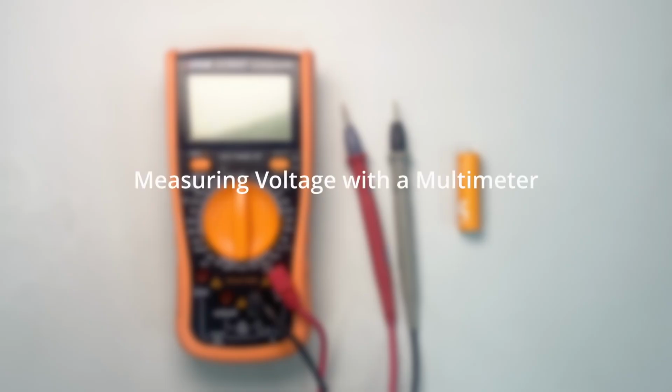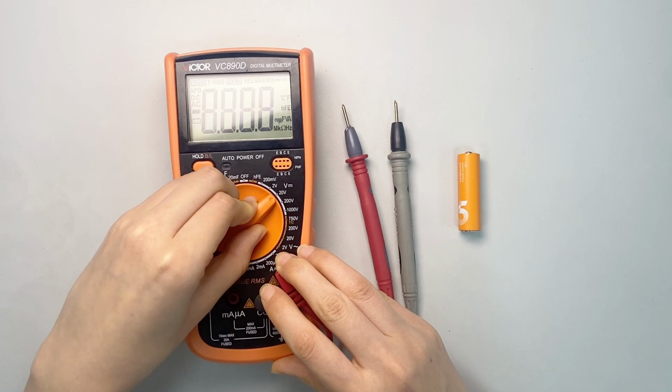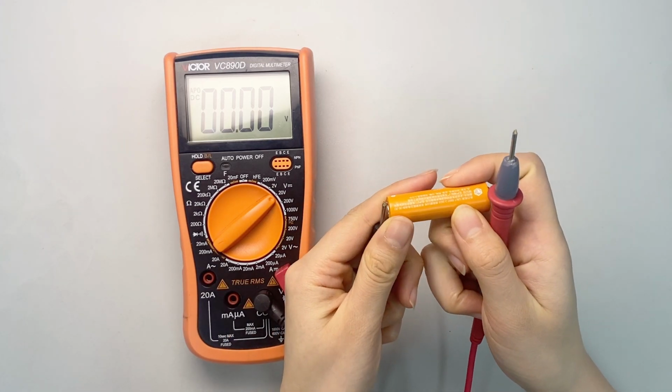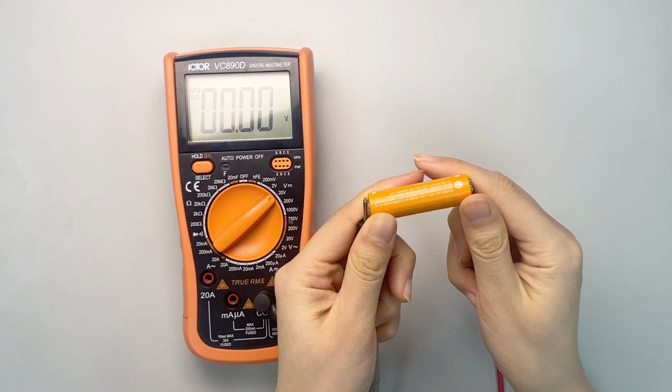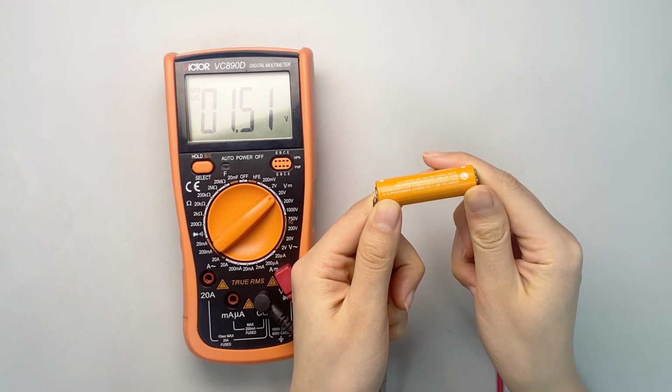Students who have a multimeter at home can measure the battery voltage by themselves. First, set the dial of the multimeter to the voltage measurement mode and choose the appropriate range. Then, touch the red probe to the positive terminal of the battery and the black probe to the negative terminal. The multimeter screen will display the corresponding voltage value.